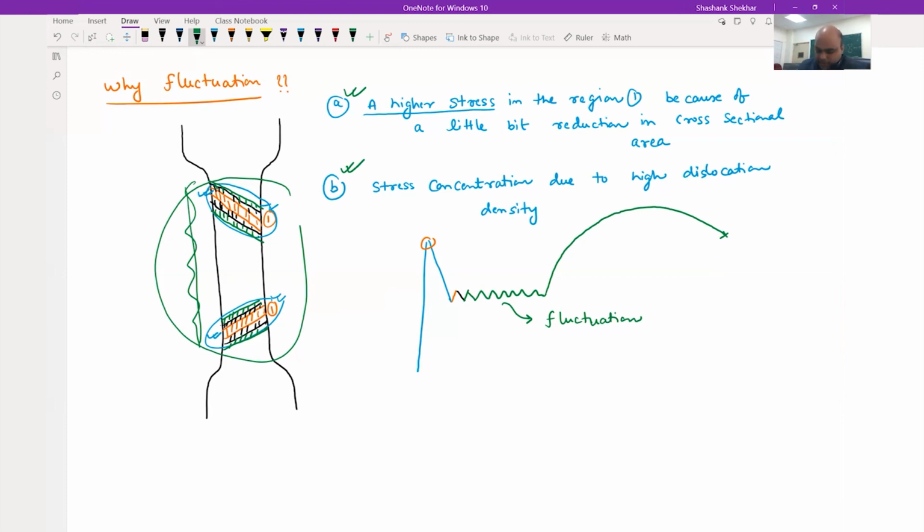Okay, and the second is that in steel industry, people use RH process where they use vacuum, and then they remove the interstitial atoms, carbon as well as oxygen they also remove. So all these are done in the steel making process itself. And the third is you can use something called skin pass rolling, or we also call it temper rolling, to get rid of this formation of Lüders bands or stretcher strains.